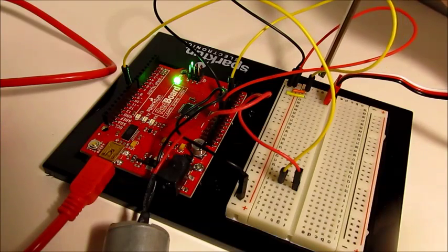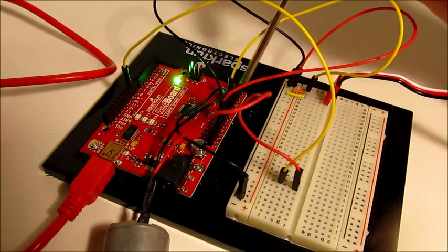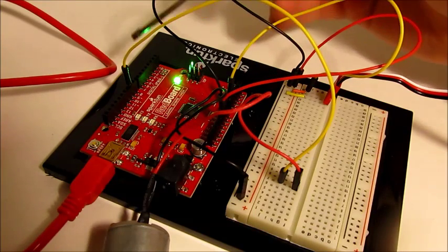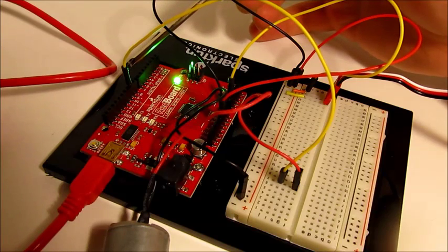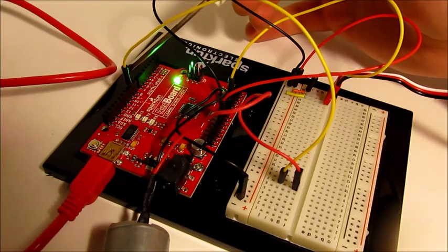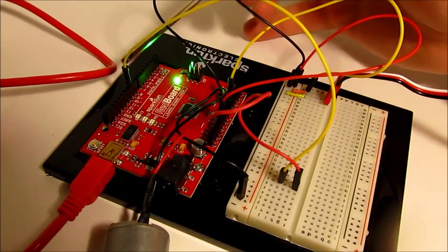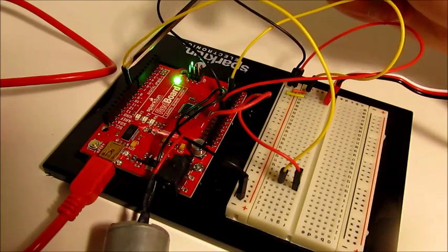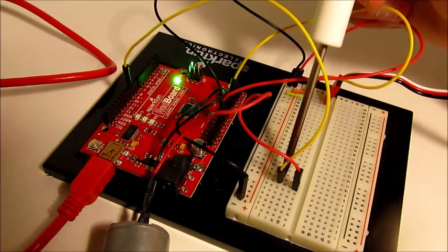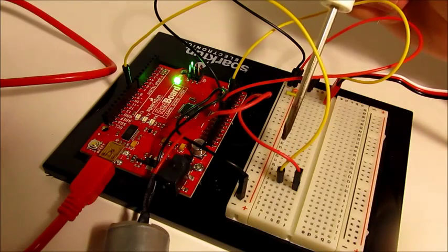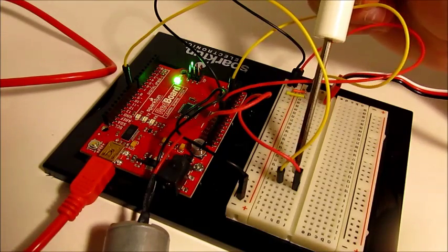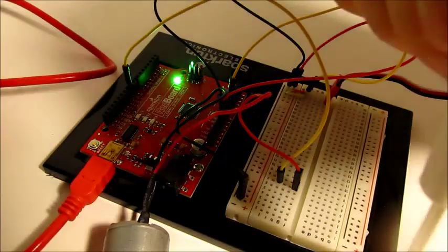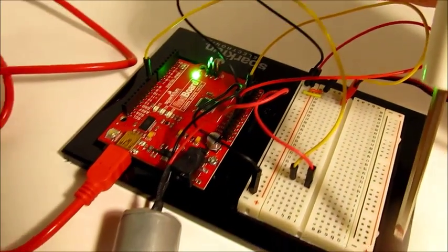The potentiometer is then sending the signal wire through this yellow wire to analog pin 0, giving an analog input to the Arduino, which then divides by 4 to get a PWM output value to pump into output pin 9 as an analog output using pulse width modulation, which then goes to the positive side of the motor. Depending on the pulse width modulation value will depend on what voltage the motor gets. This then goes through the motor and back to the ground bus, where the motor is plugged in.